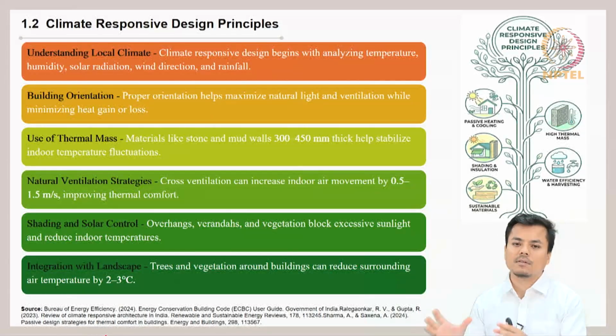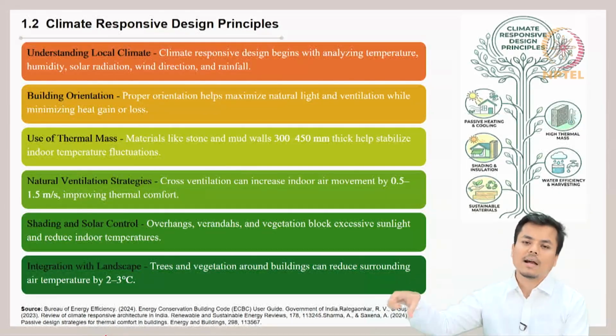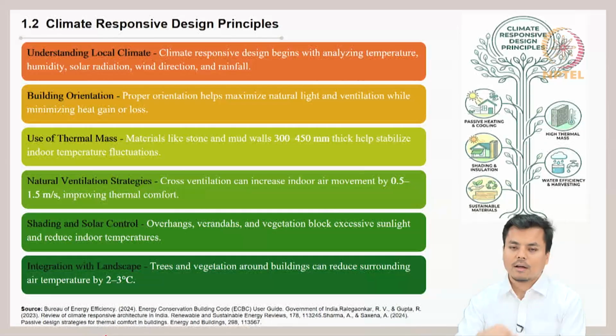These rooms, since they are not in direct contact with direct sunlight, will have a much lower temperature than the rooms where there is direct entry of sunlight, because it is completely impossible to design the entire building where direct sunlight is not allowed, unless you design verandas all along the residence.